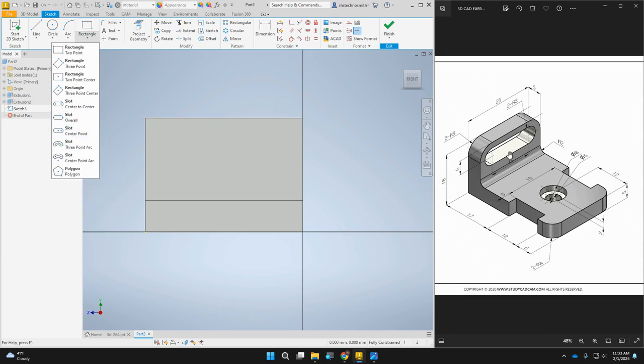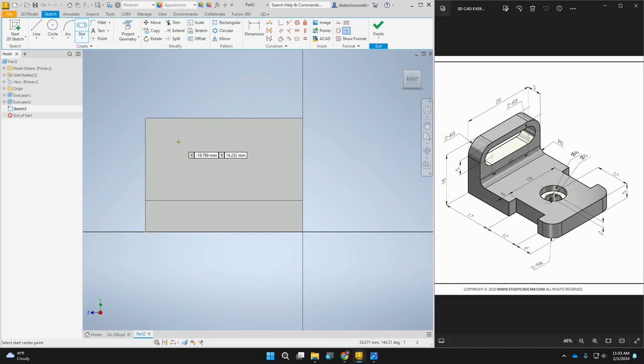So if I look at it, I notice that there is a measurement between the 2 circles. So that is a center to center slot. And the way it's drawn is you click and draw the line that goes across, and then you give it thickness. It's kind of cool, right? And it adds all those constraints and a whole bunch of stuff I don't have to do. If I was to make it with a rectangle and circles, I'd have to do a lot of lining up. So that's pretty cool.